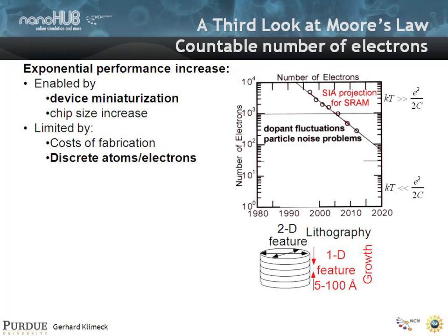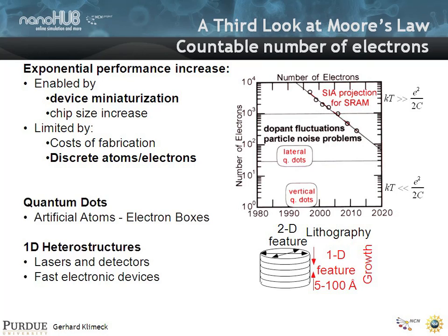And another way to look at it, well, maybe you can operate in a different regime where the charging energy would be much larger than the thermal energy. And if that's the case, you can talk about quantum dot type devices of single electronics. So that's another alternative people are starting to look at, or have been looking at, which is single electronic devices. And they have their own problems too.